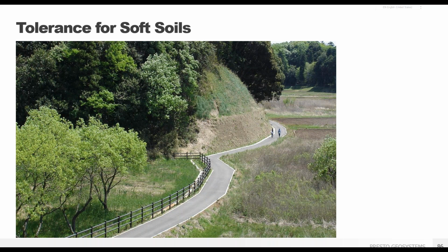Using the GeoWeb system can help avoid expensive and time-consuming activities such as surcharge loading a site, which often has to happen when differential settlement is a concern. The time required for the surcharge loading may be reduced or even eliminated when using a GeoWeb wall. It also reduces the amount of visual inspection maintenance and repair over the lifetime of the wall structure, since the GeoWeb panels can accommodate much more movement than any masonry wall.